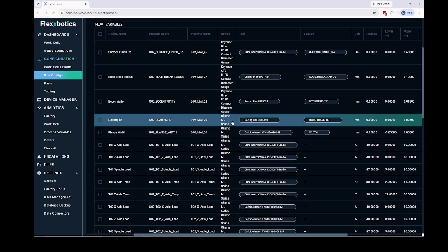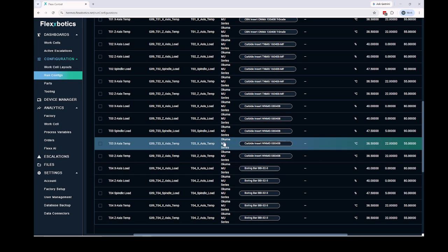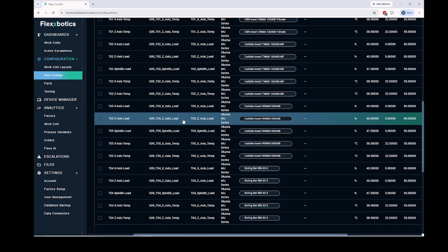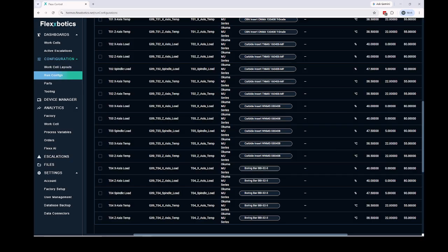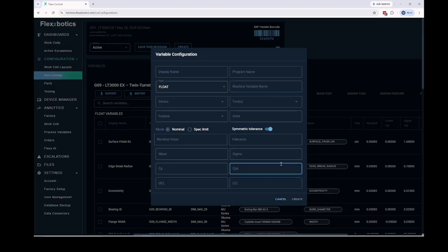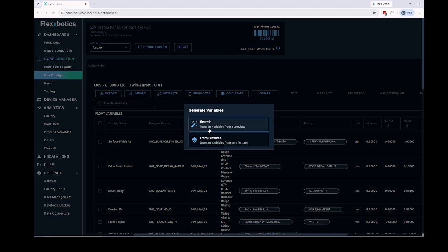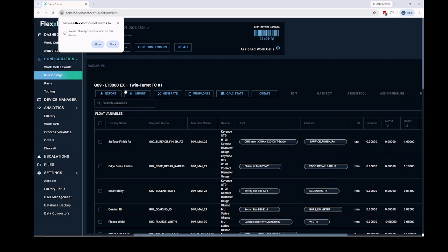Similarly, we have live runtime data from our CNC and FANUC robot, collected at different frequencies and tied to specific tools and operations. All variable data is collected based on data events generated in real time, organized by work order, device of origin, and with respect to specification and control limits. Making new variables is a straightforward process, and we provide templating tools to both generate variables and also distribute them across different similar cells en masse.